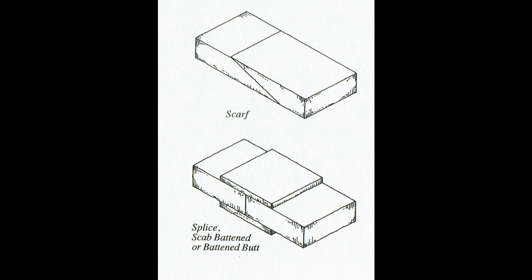As most lumber types come in standard or nominal sizes, there may come a time in which a project requires you to build something much larger. The scarf joint would be the joint that you would want to use in order to extend those boards and keep everything together. This particular image here is the preferred method, as it provides a lot of surface area for the two boards to basically be touching one another. You'll typically have to have what is known as a scab added to either side, as shown here, to ensure that that joint stays together through the build process.